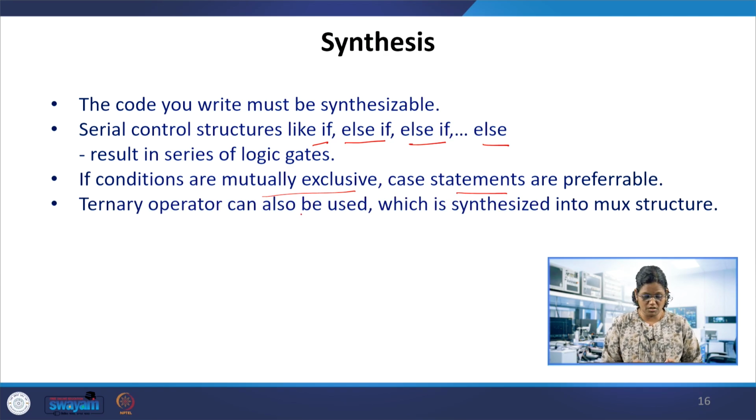Suppose, for example, the ternary operator. The ternary operator has a logic expression, a question mark, the true expression, a colon, and then the false expression. If the logic expression is true, the true expression is assigned; otherwise, the false expression is assigned. In that case, mutually exclusive conditions are specified, so it is synthesizable, and it is synthesized to a mux structure.